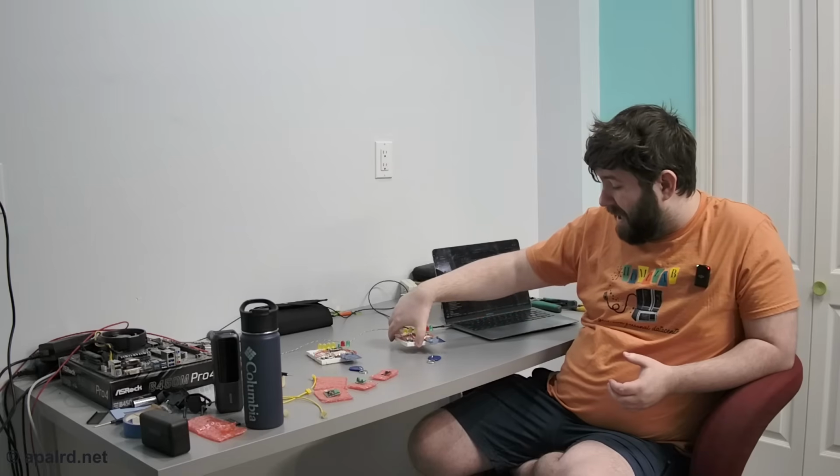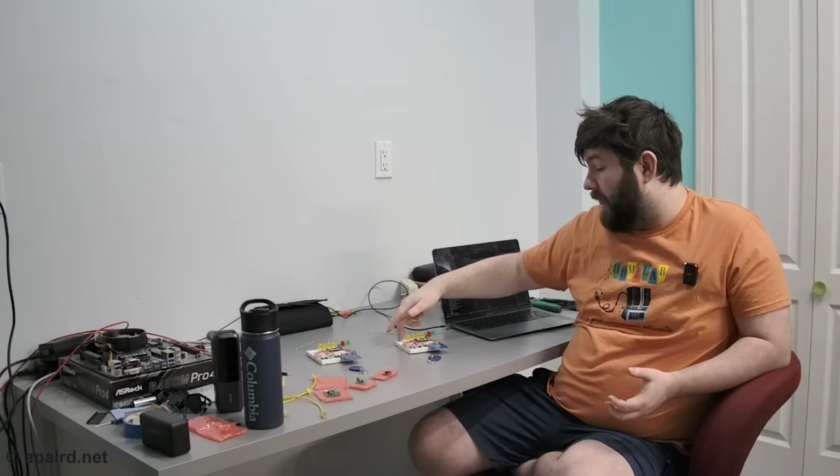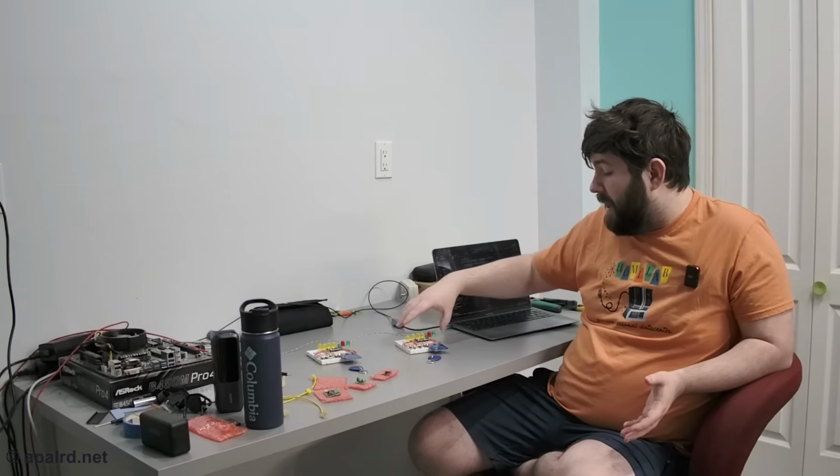And if I wanted to flash one of these modules, I would have to allocate one of these multicast addresses for flashing that module, or we'd have to go through some rigmarole of taking control of that temporarily for the flashing purpose. But with this, I'm on Ethernet, so all the rules of Ethernet apply. I have broadcast, which we don't use that often, but I have multicast, so I can use multicast groups to sort of simulate what we had on the CAN bus. If I want to send data between these two nodes, they can send it to a multicast group ID. But I also have unicast. So if my laptop wants to do reflashing or something, it can get the unicast IP address of one of these boards and talk to it specifically.